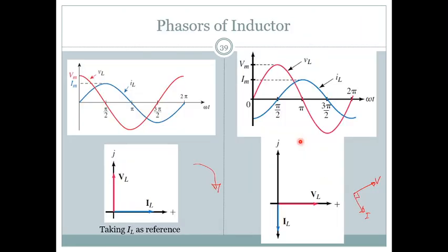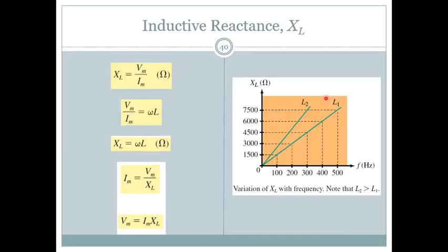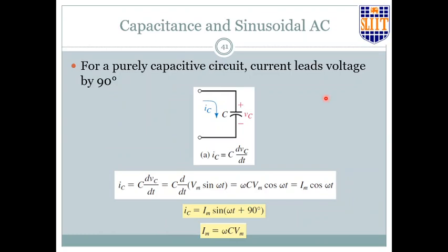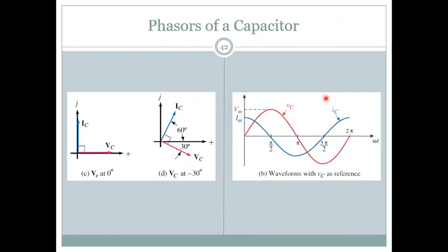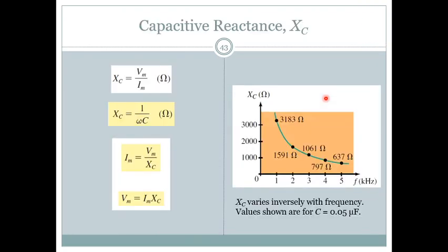If you look at the inductor waveform, let's take the falling edge. For that falling edge, the falling edge of the voltage occurs here, exactly another half a pi. Current is falling, zero crossing is there, so current is lagging in this case, voltage is leading. But for the capacitor, it is the other way around: voltage is lagging, current is leading.